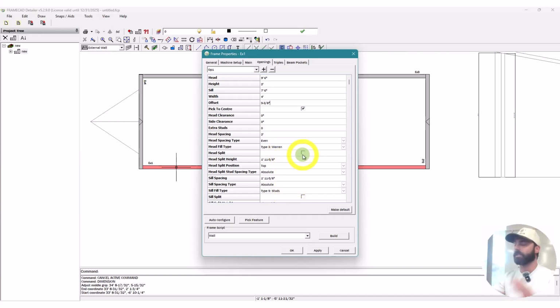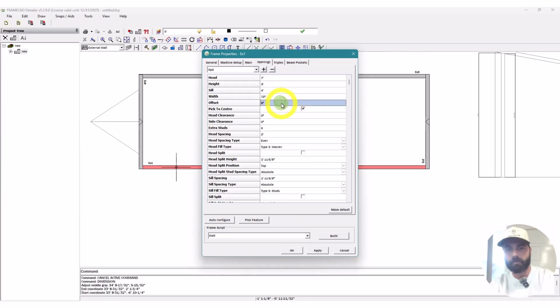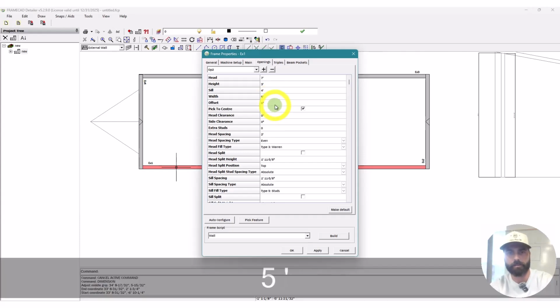So let's say this one, we'll do a 7-foot header height for speed. They want a 3-foot tall window, and that's going to be 60. We'll do a bigger loft, so we'll do 70. We'll do 6 feet off of the end of the tiny house. Sorry, we'll do 3 by 6. We'll do a 3 by 5 window. 72 inches off the end of the tiny house.